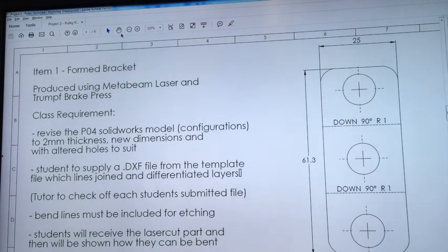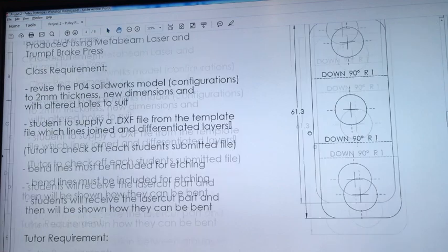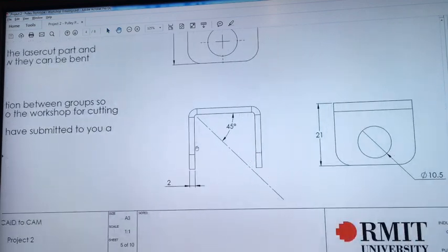I'll just zoom in a bit so you can get to see that view. Okay, from this drawing view here, if you imagine the forming tool come in there, if these edges were any bigger, then it wouldn't be able to bend it the 45 degrees on both sides. Okay, it would prevent it, all right, because this part of material would be hitting that tool. All right, so that's why we have to decrease the total height to 21 for the prototype version.